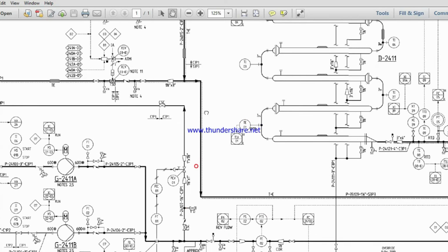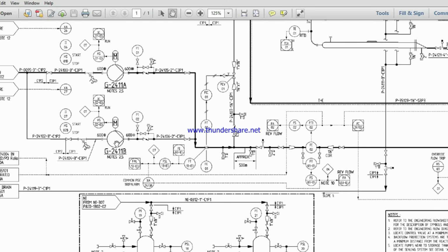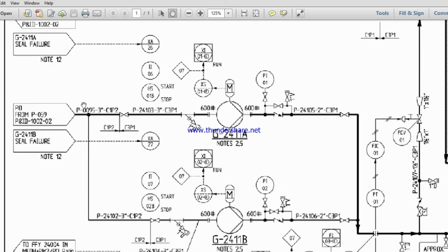All the mechanical equipment is to be shown in the P&ID, like here the pump is shown with its unique tag number. All nozzles on equipment items must be shown in a roughly accurate location, whether for piping connections, instruments, vents, drains, or spares. All the nozzles must be given tag numbers. The pipework representation is non-scalar and entirely symbolic at this stage.